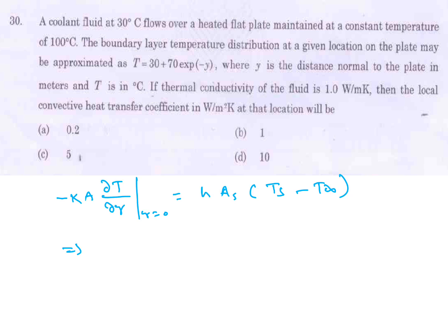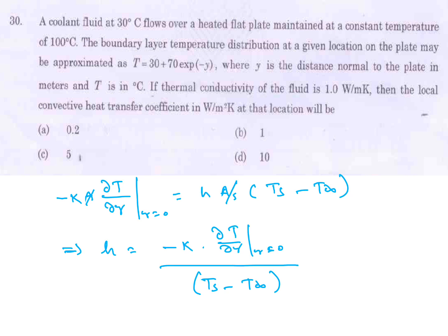Here they asked the local convective heat transfer coefficient: h equal to minus k dT by dy at y equal to 0, divided by Ts minus T infinity, surface temperature minus outside fluid temperature.